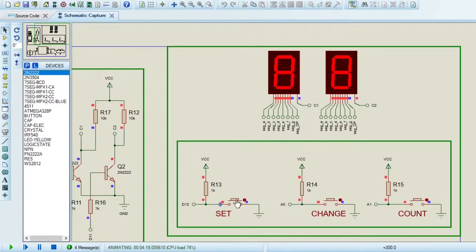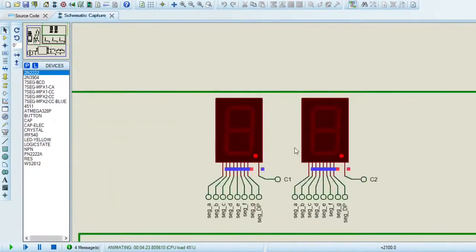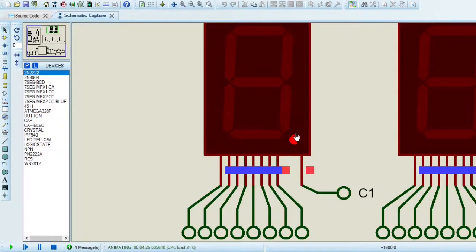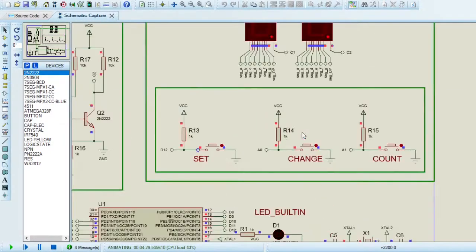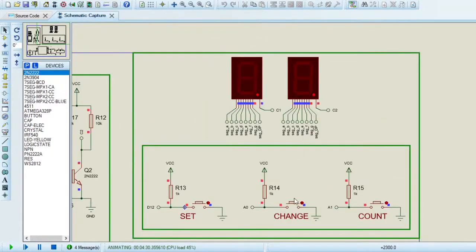If I press a second time, I turn off the 7-segment displays, and the third time I can see how the dot point segment in the 7-segment displays are turned on. In this stage, I can configure the initial count with this second button.